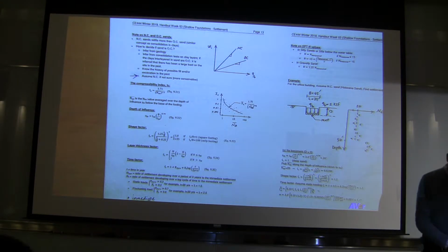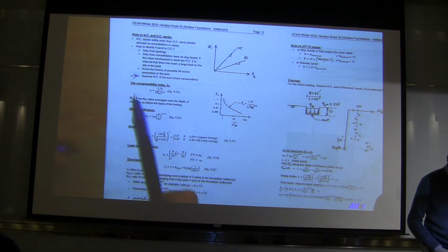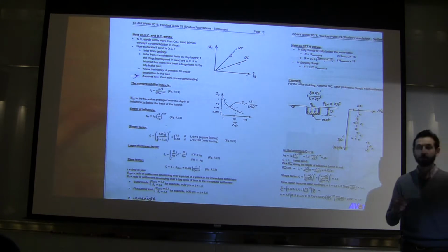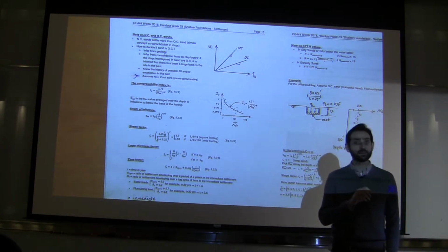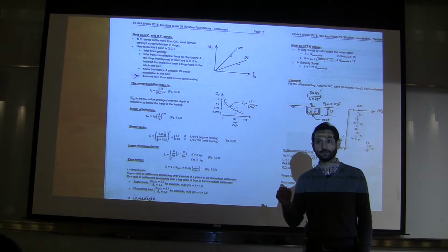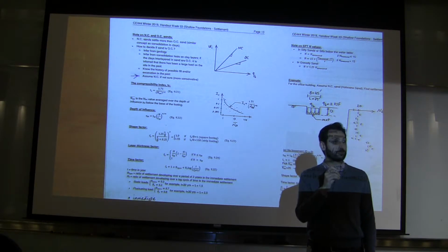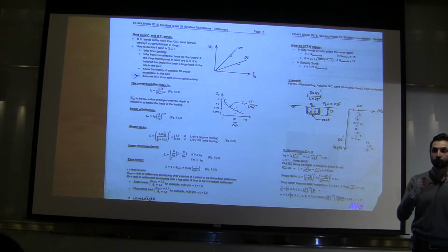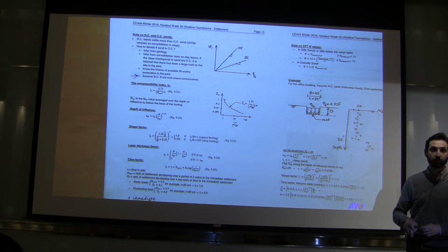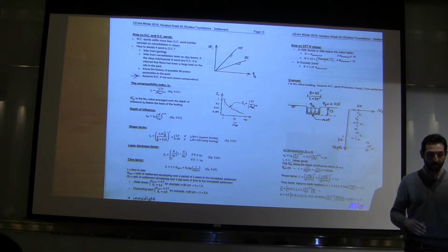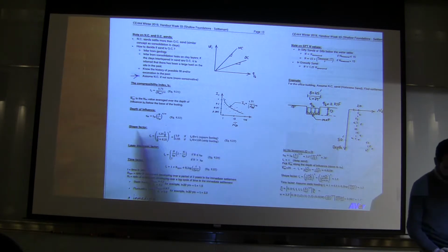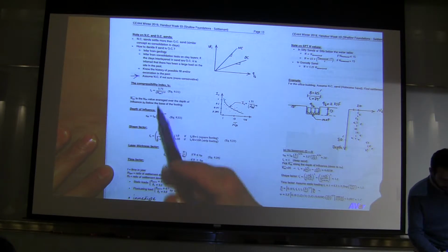All right. Now we get to this interesting one, the compressibility index, I sub C. And I want to make a comment here, not to confuse this I sub C with something that we had for CPT. Remember that soil behavior ratio, I sub C, for CPTs that we used to find the type of soil, whether it's sands or clay or gravel, based on those zonings. This is not the same I sub C. Okay, so don't confuse it with that one. And it comes with this equation.